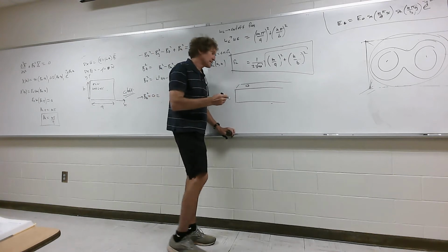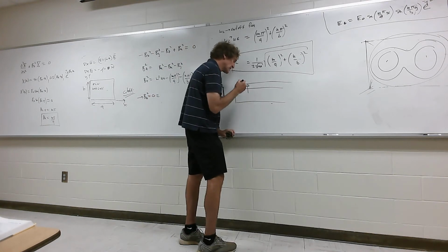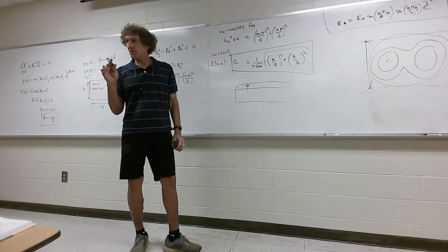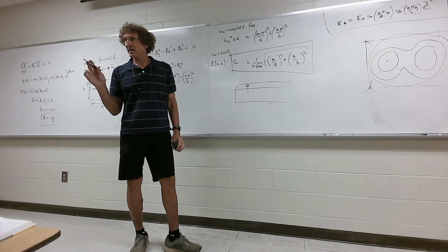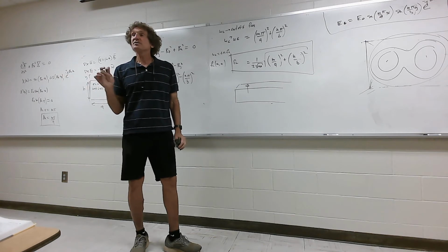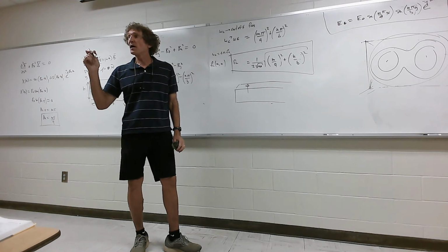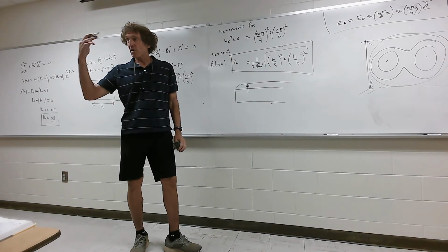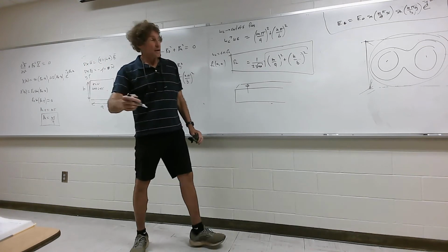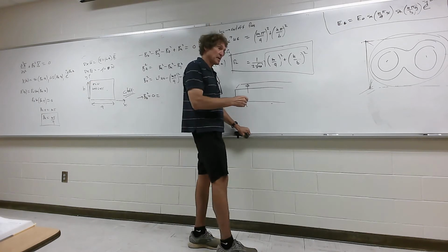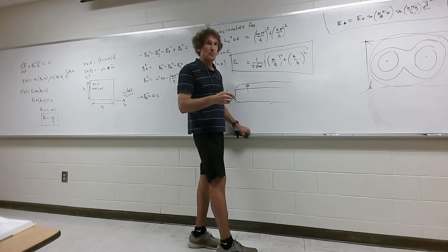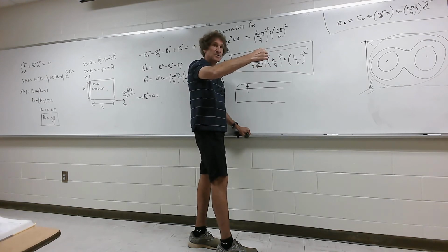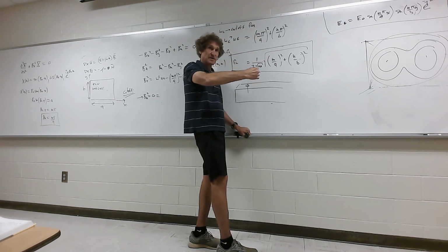And they're going to drop an antenna in here, straight through, and the antenna will have a depth so it'll be impedance matched. This is way beyond what we can talk about here right now. You haven't even had an antenna here. Then when it's impedance matched and it's in the 1-0 mode, the lowest possible frequency will propagate in only that mode. And what will happen is, if it's a 1-0 mode, you'll basically get a sine wave variation in the x direction and no variation in the z direction, right?